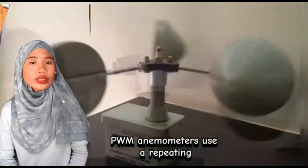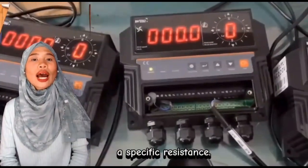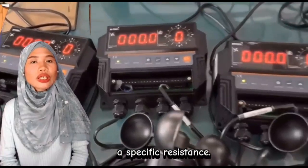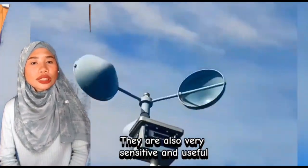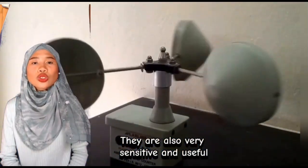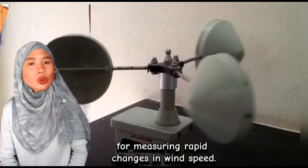PWM anemometers use a repeating pulse of current to heat the wire up to a specific resistance, and the length of the pulse is then used to infer the velocity. They are also very sensitive and useful for measuring rapid changes in wind speed.